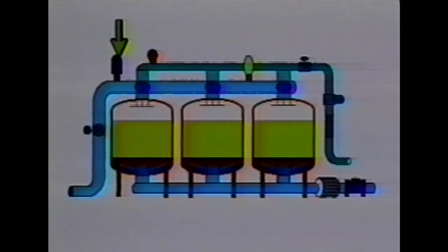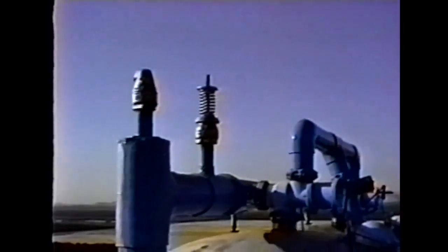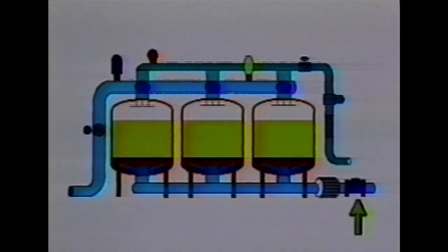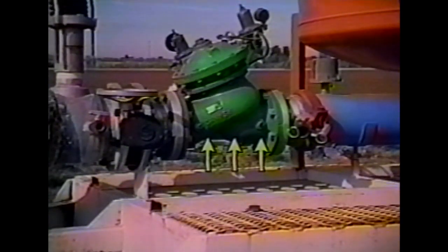A pressure relief valve is located upstream of the filters. It is used to protect the filters from overpressurization and damage from water hammer. A pressure sustaining valve is required on many systems. It is needed when the water supply cannot meet the flow rate to the system and to the filter during a backflush process. That scenario was discussed earlier in this video when it was suggested that 2 tank systems not be used. However, if a pressure sustaining valve is needed, one of the new low pressure loss designs should be selected.